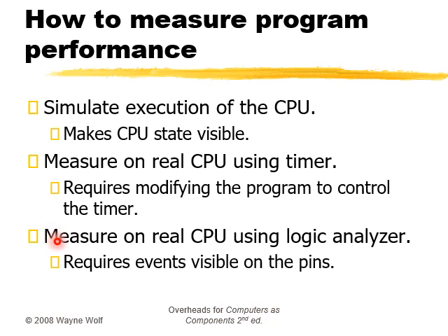Finally, a logic analyzer can be connected to the microprocessor bus to measure the start and stop times of the code. So we can use a logic analyzer and connect it to the CPU bus. It requires events to be visible on the pins. Pins basically means the buses. So this logic analyzer requires events to be visible on the bus.